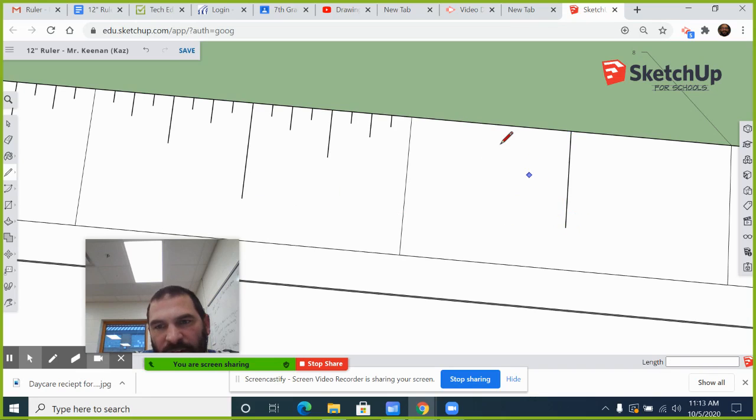And each time, I'm not saying it out loud, but every time I draw, I hit escape so that it unsnaps itself from the drawing. So I'm not making pencil lines all over the place. After I click once and click twice, click once, click twice, I'm hitting escape every time once the line is drawn, because it essentially lifts the pencil off the paper. If you don't, the pencil stays on the paper, and wherever you move your mouse, that is going to stay on there. Whoops, it's going to mess people up.